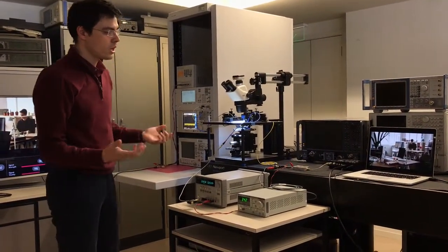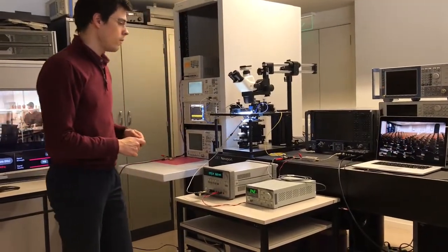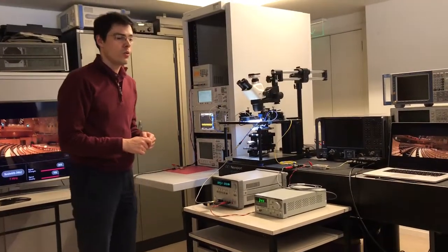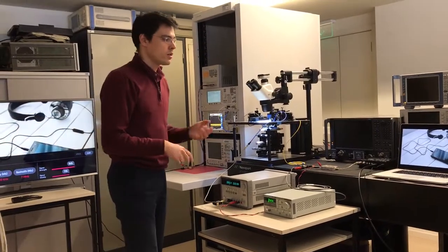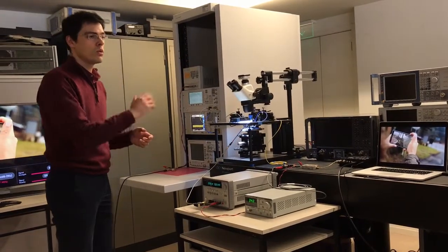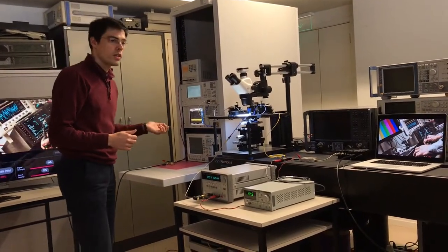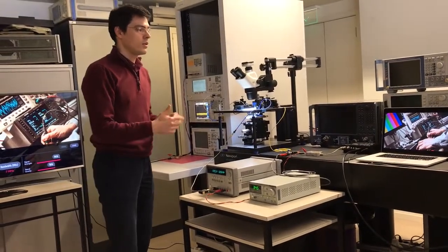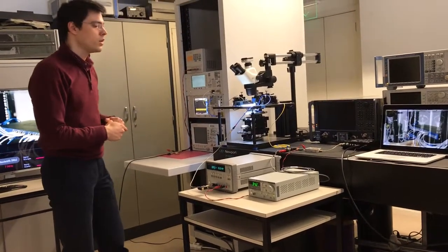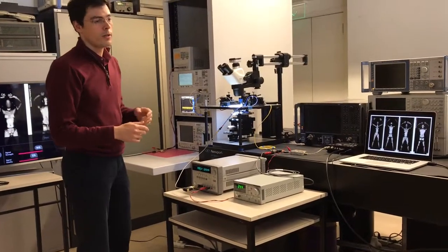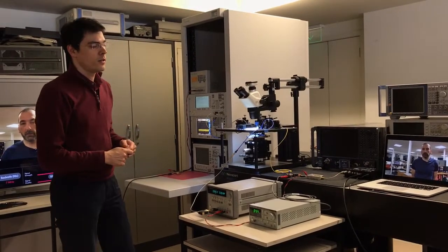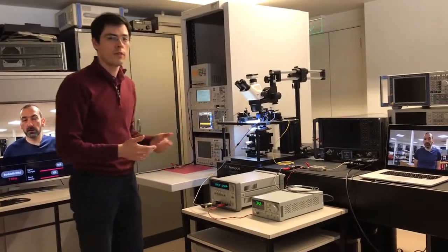This demonstration is actually a proof of concept of the ability to modulate the RTD-PD with an optical signal, subcarrier based signal, and to transfer this signal to the RF domain, in this case 13 gigahertz. But ultimately it shows the possibility of using the RTD as an interface between optical networks and the wireless domain in the future, possibly at very high frequencies.